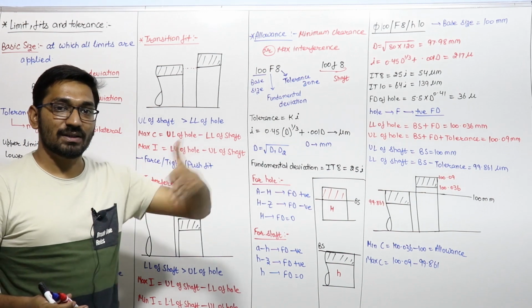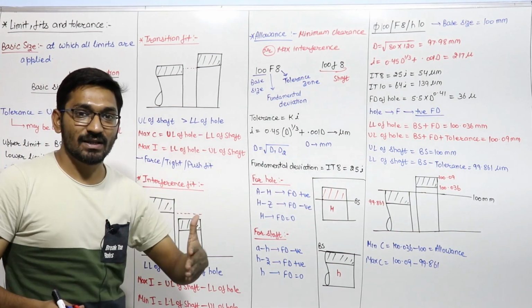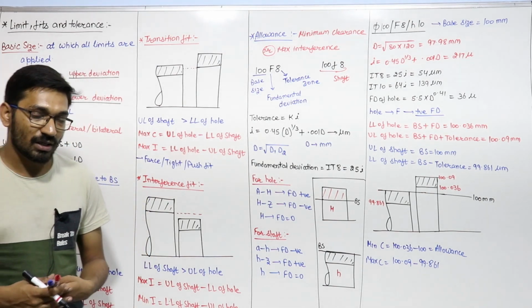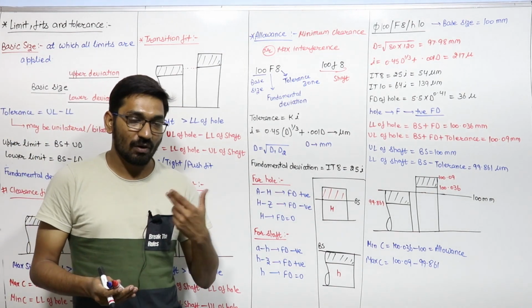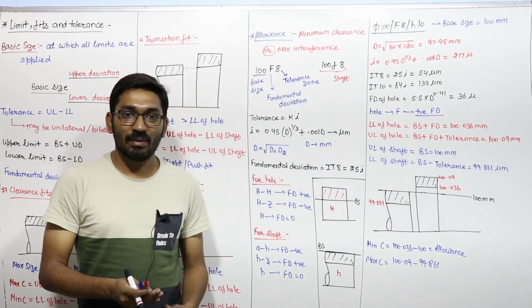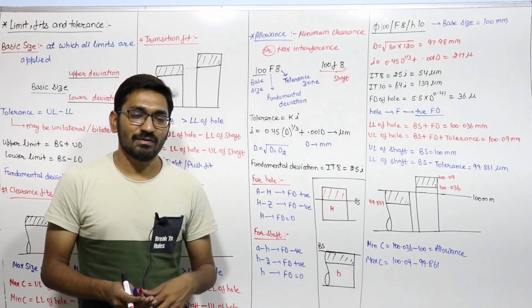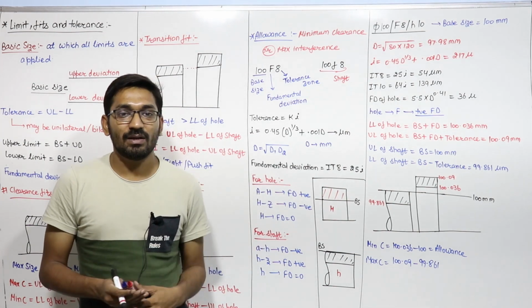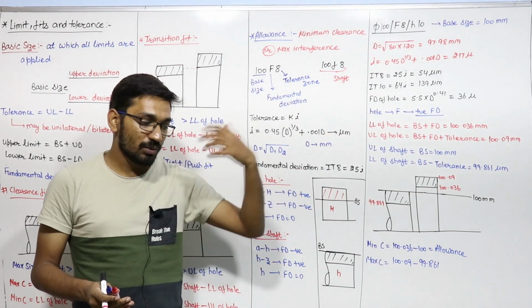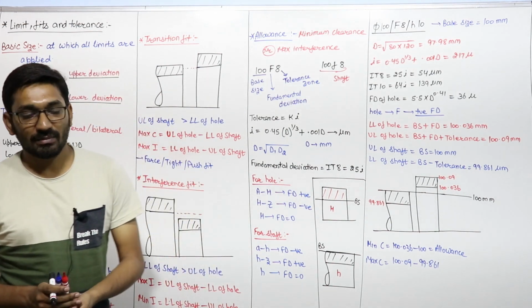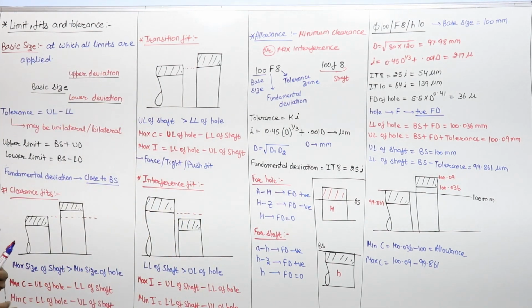Then this is the deviation to its actual basic size, how much we can deviate, because the manufacturing process is not 100%. It means that if you need a 100 mm diameter, it is not possible to make 100 mm dia itself. There must be some tolerance, that is 100.01 to 99.99. So because of the manufacturing error, some limits and fits we have to take care of.